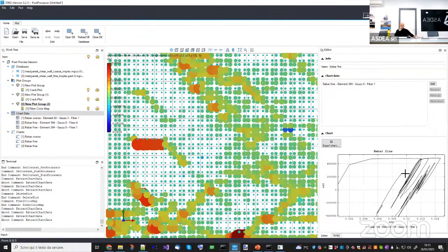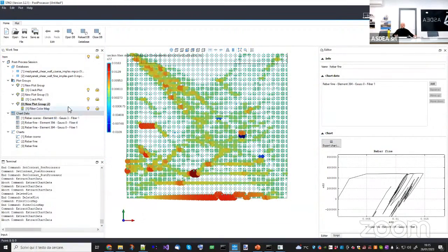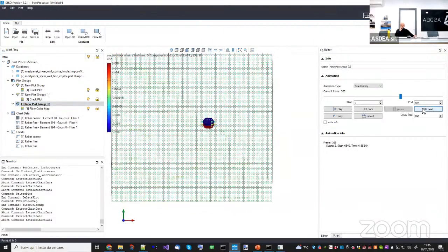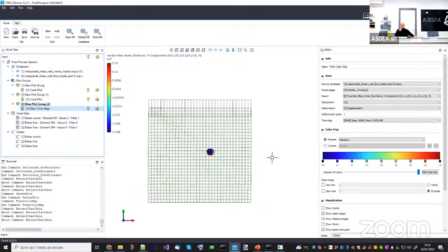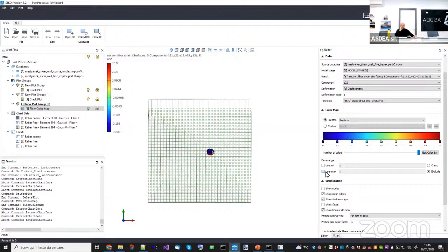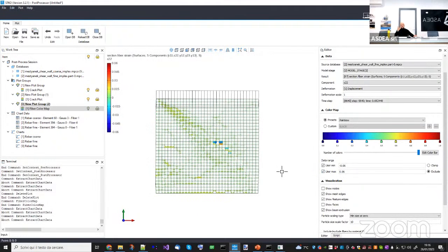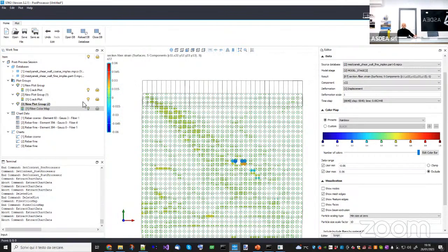Okay, so this is a rebar here. I'm developing more deformation, but if I pick some other of them, I will see much more deformation also. You can see it clearly from here, okay? So as I keep on increasing, you have some of these values which actually should be broken, but if I clamp the values to, let's say, a maximum of and a minimum of minus 0.06 and 0.06, because I didn't input the maximum deformation, you can see that some of them are very close to this value, okay?